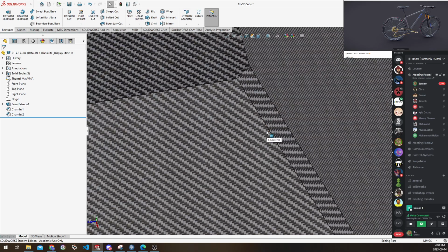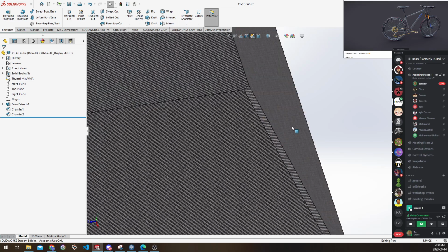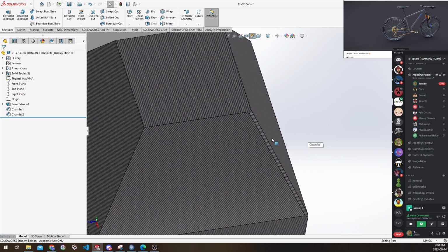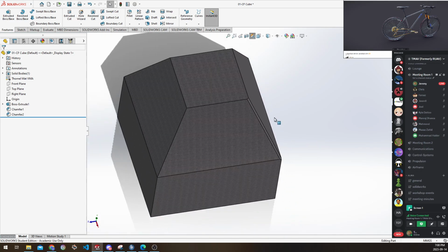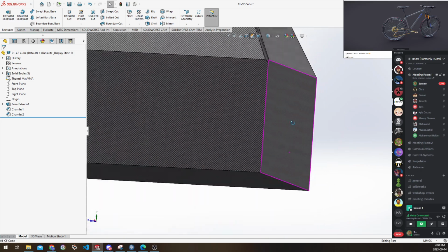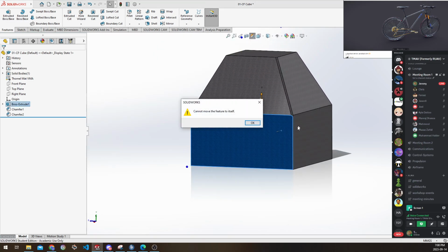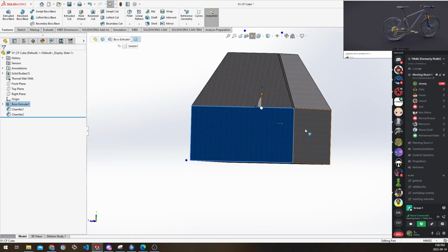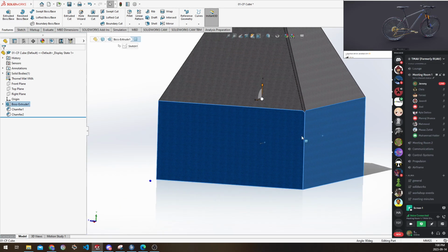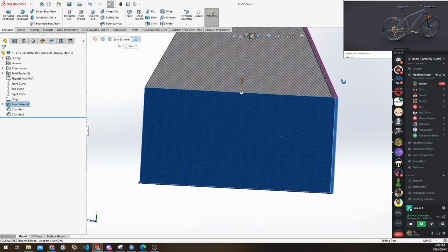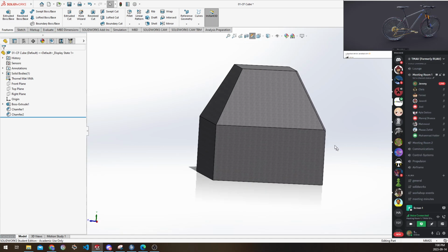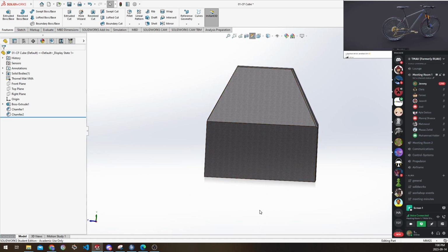The second is when you're designing molds for plastic, you want them to be as smooth as possible. It makes it a lot easier to get the parts out of the molds. And typically, one of the biggest use cases for chamfers is, for example, this would not be a moldable part. The reason for that being is that these surfaces are perfectly parallel. You see they're 90 degrees, right? And so if you were to put this into an injection molded part, you wouldn't be able to get it out. If you tried to pull it out, there'd be so much friction on the sides between the part and the mold that it physically would never be able to come out. You need some kind of angle in, right?